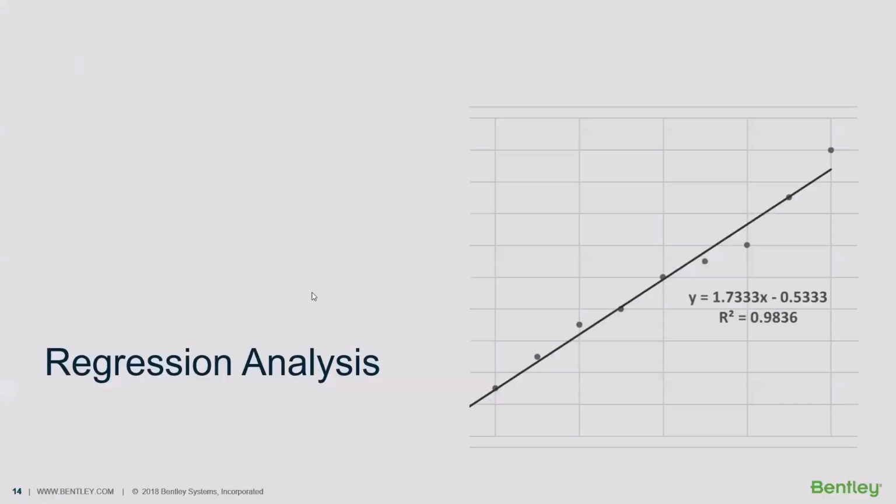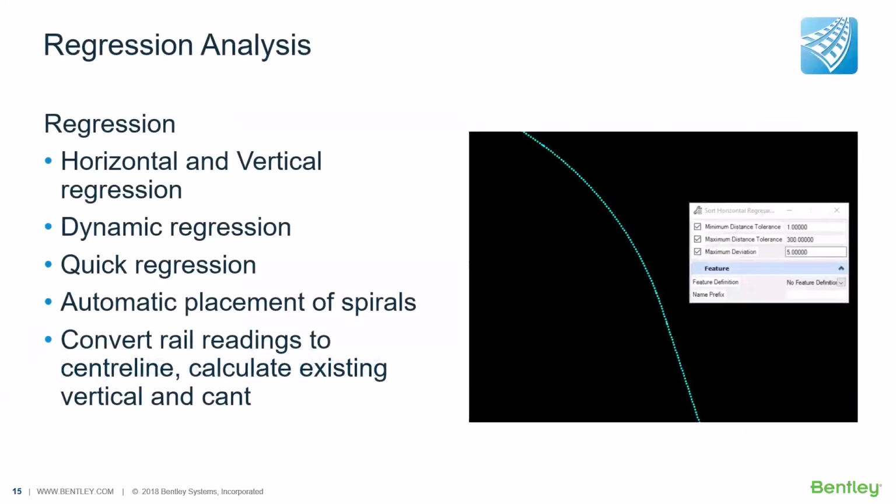So what do we have in this particular case? We do have a new geometry that can be designed, right? We have the option to create a new horizontal geometry straight from the geometry section, or the geometry tab, that we have in OpenRail. The other thing we will come across is the rehabilitation of tracks, right? That's going to be one thing. For that, when we collect the data from the surveyor and then use it, that's where the regression analysis tool is going to be helpful.